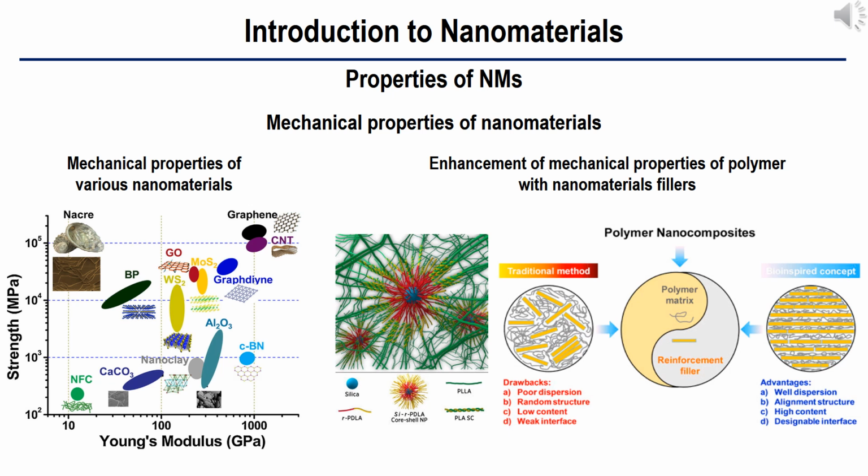Among the most exciting nanocomposites are the polymer ceramic nanocomposites, where the ceramic phase is platelet-shaped. This type of composite is preferred in nature, and is found in the structure of bones, where it consists of crystallized mineral platelets of a few nanometers thickness that are bound together with collagen as the matrix. Composites consisting of a polymer matrix and exfoliated phyllosilicates exhibit excellent mechanical and thermal properties.